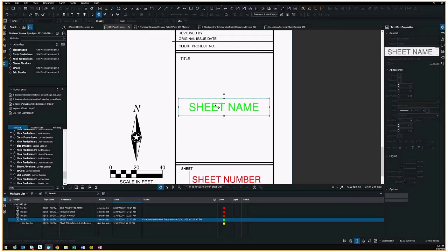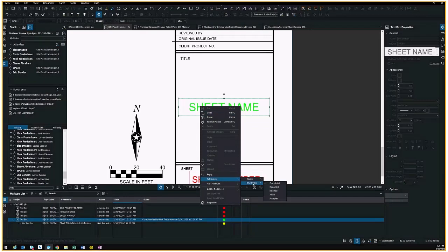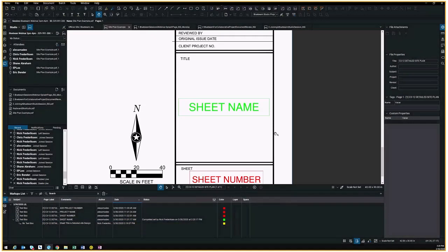So that red line, or that comment, that markup is completed, is taken care of. I don't have to worry about that anymore. As you can see, the color did change here for us on there. We've set up some of our own profiles here so that as things are reviewed and status changes to completed, canceled, rejected (no, we're not going to do that), or accepted, it will change color for us. So we do red to green to show that that is completed. How that's beneficial is green means it's done, so it's a visual representation.